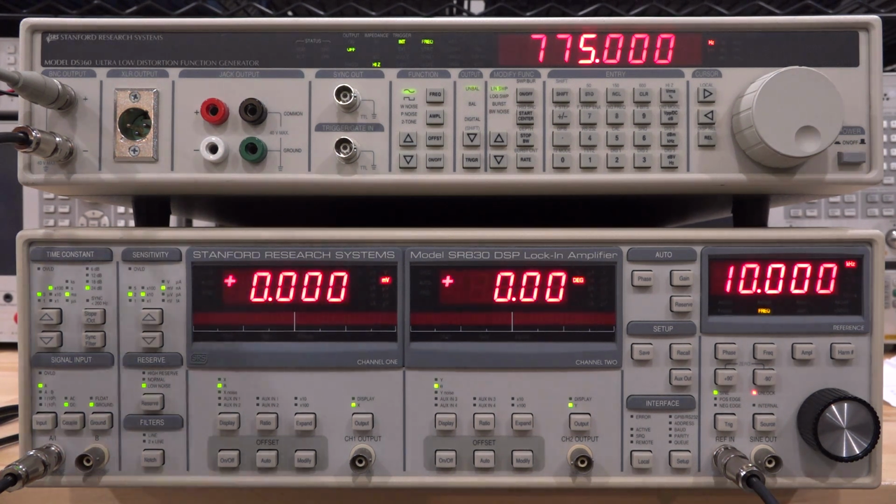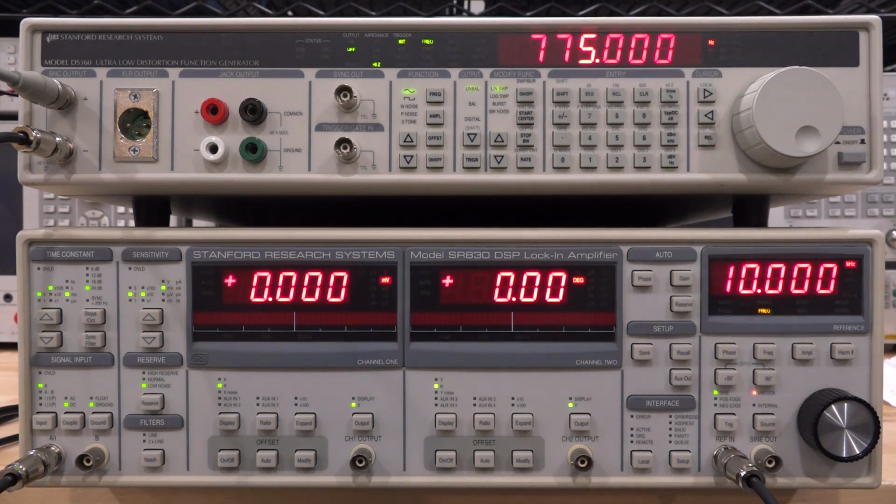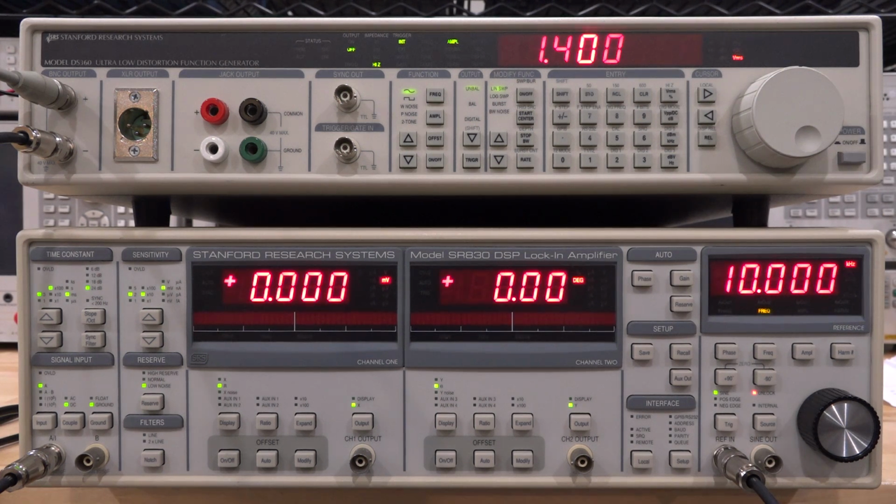So how does the setup work? We have the output of our synthesizer, the low distortion synthesizer at the top over here. It goes into the filter I just showed you, and the output of the filter comes back and goes into the A input of the lock-in amplifier. So basically, output, filter, input. So far, so good. But then a lock-in amplifier needs to lock to a certain frequency in order to be able to measure the powers you're looking for at different harmonics. So we have a 775 hertz signal, which is the center of that filter. And the amplitude of that signal is 1.4 volt RMS. That's the condition we're going to do this measurement.